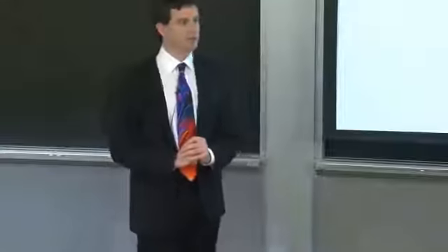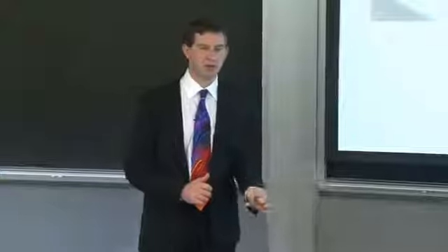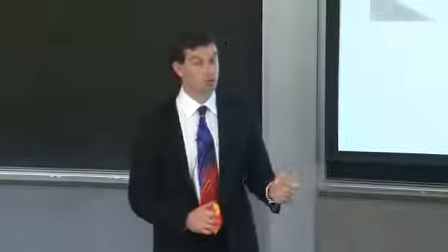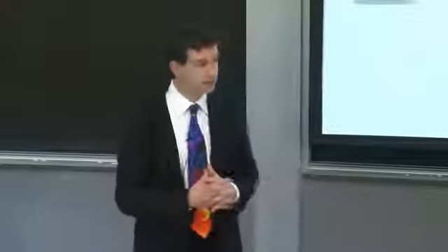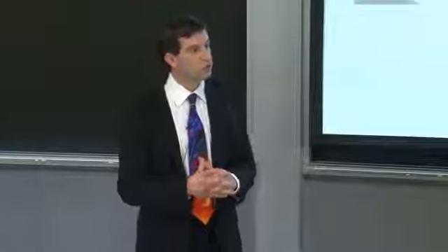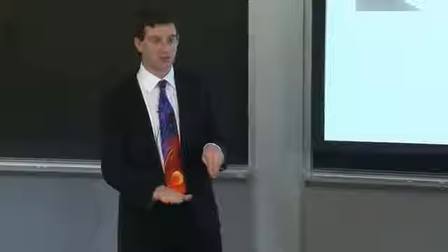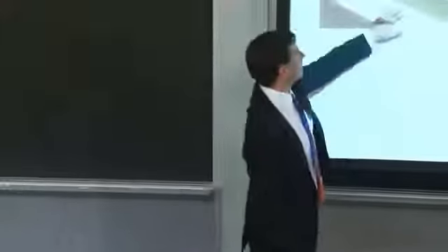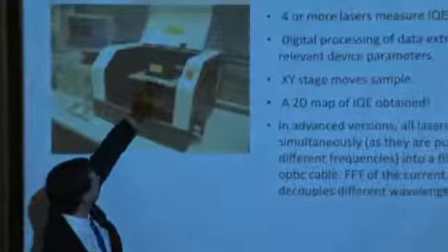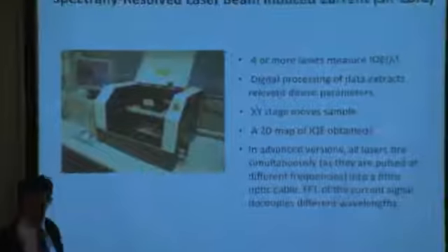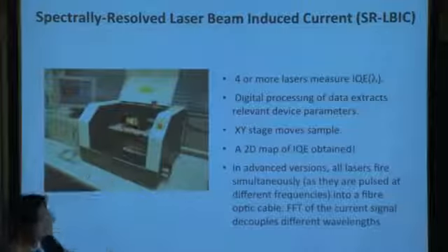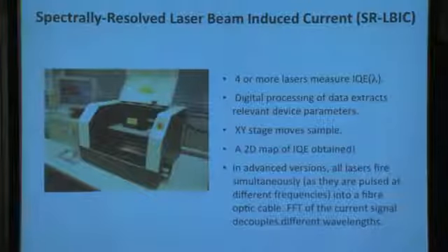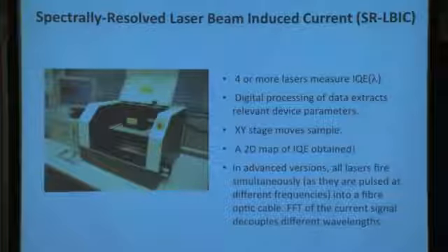Well, in one incarnation, you would use a much more finely focused beam. Instead of having something on the order of a millimeter, you might shrink the beam spot size down to the range of single microns, and then use an XY stepper motor to scan across your device. And that's precisely what this does right here. This white piece is the XY stage, and this black head right here is comprised of several lasers that will shine onto the sample.